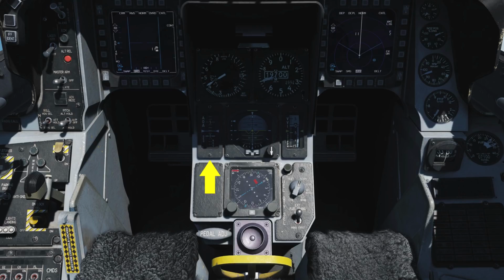The bar in the center of the tape indicates your current angle of attack in relation to the center of the tape. The Attitude Director Indicator, or ADI, displays the aircraft's pitch and roll attitude as supplied by the Inertial Navigation System, or INS. The indicator also includes a turn rate needle, where the needle's width equates to 1 to 1.2 degrees per second, and a ball and slip indicator. The pitch trim knob can be used to adjust the sphere in relation to the aircraft symbol. When the instrument landing system is enabled, the ADI can also display the localizer and glide slope bars along with associated warning flags. We'll talk about this later in an ILS video.